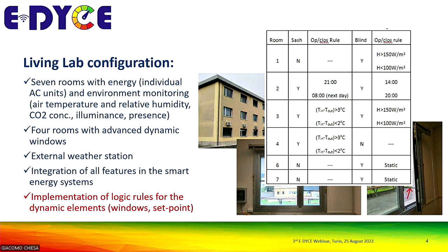In this table, as an example, we reported the logic control for solar shading activation and window opening according to time schedule of physical parameters that are measured inside the building or in the external weather station we have mounted on the building itself.